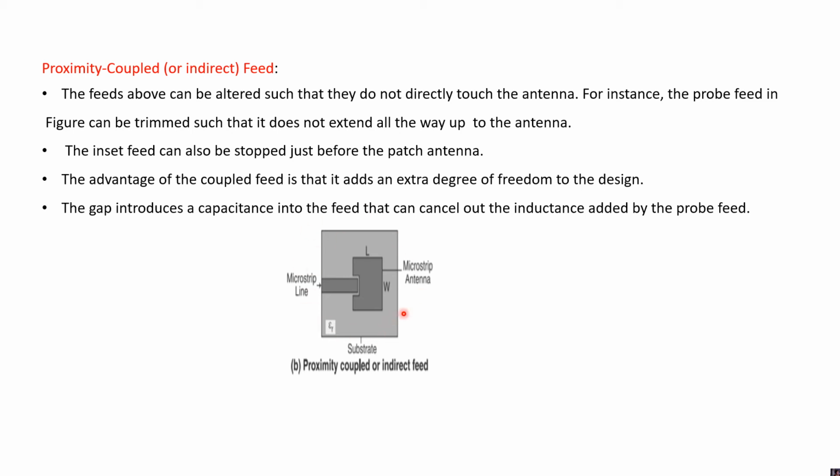The advantage of this is it adds an extra degree of freedom to the design, but the gap will introduce a capacitance and it will cancel out with the inductance added by the probe feed. So these are the different feed mechanisms you have.